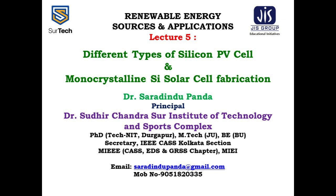The solar cells made of crystalline silicon are often called the conventional, traditional, or first generation solar cells, as they were developed in the 1950s and remain the most common type up to the present time, because they are produced from 160 to 190 micrometer thick solar wafers, that is slices from the bulks of the solar grade silicon. They are sometimes called wafer based solar cells.